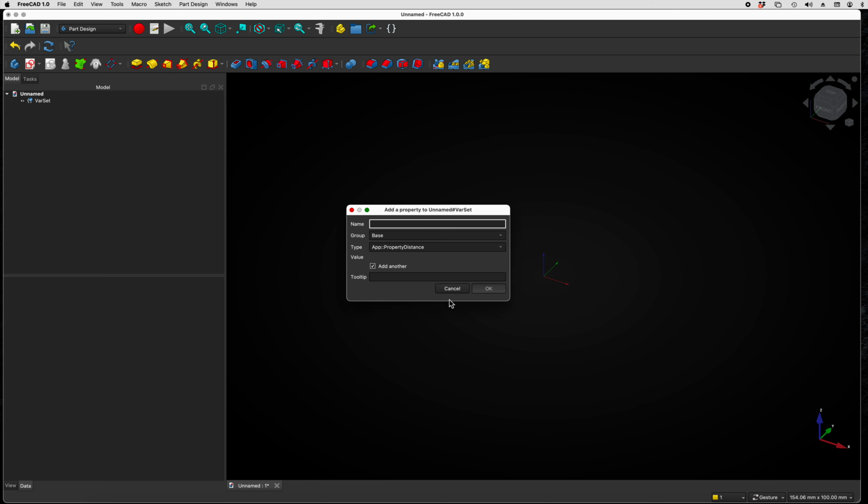Now moving on then to the body inside, we're going to define the inside diameter. Now the inside diameter is going to be the container inside. So we've already reduced the body diameter by 4 millimeters to make the lip for the top to sit on. So we better make the inside diameter even smaller than that.